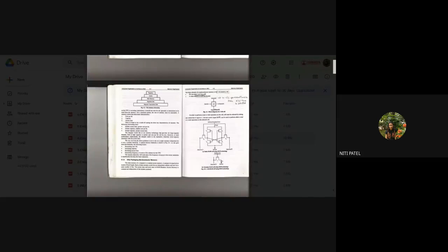Every memory cell will keep performing this until your program generates a final output. Input will be taken from the input line, and output will be generated from the output line. As soon as the input is selected, the select signal also starts working, either set to 0 or 1. If it is 0, the read write line does not have to work, but if it is 1, read and write can do the work of reading as well as writing. Once the work is completed, the select line is again set to 0. Whenever the cell performs, the select line is 1. Whenever the cell is inactive, the bit is set to 0. That is how your memory cell works.